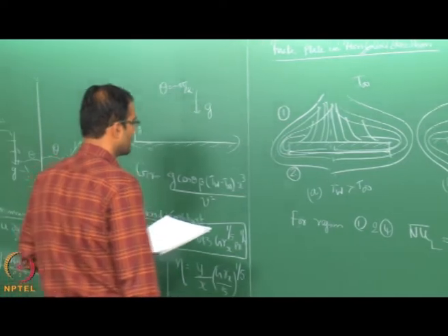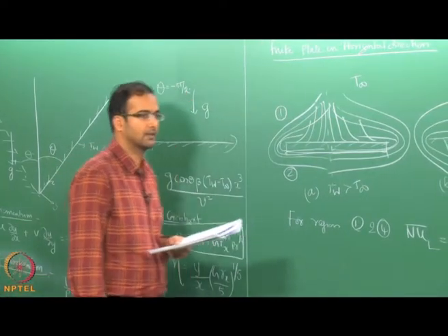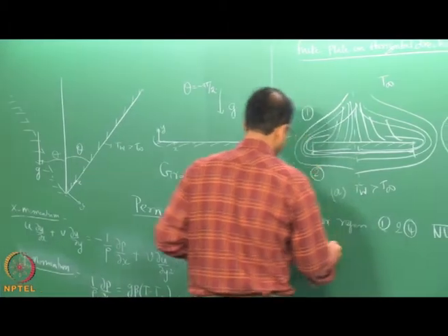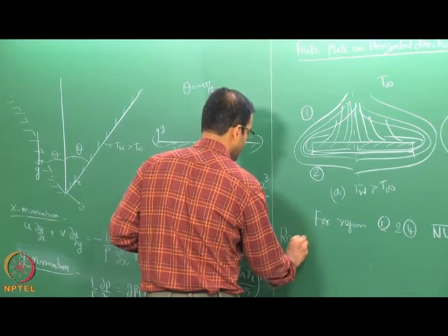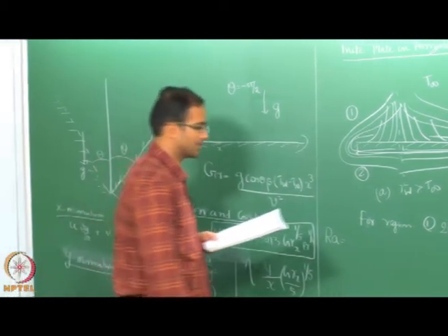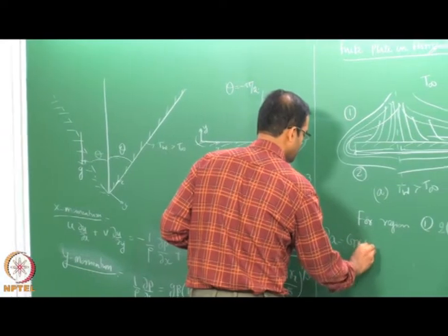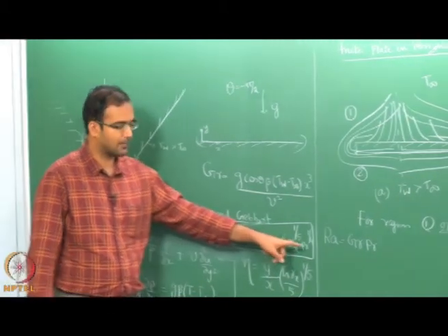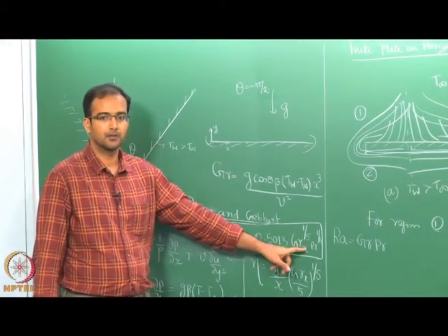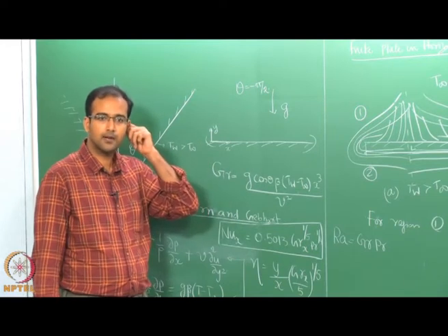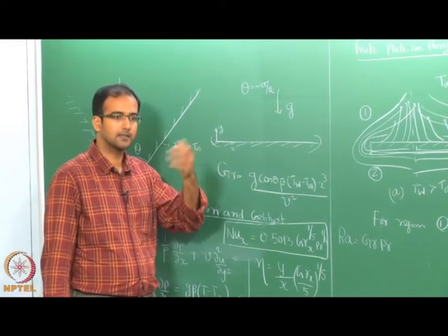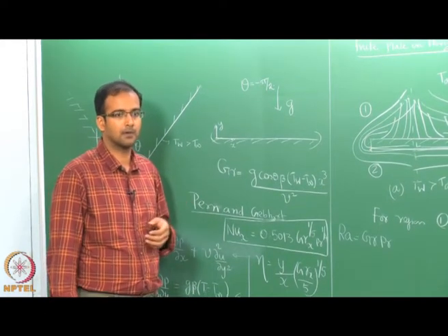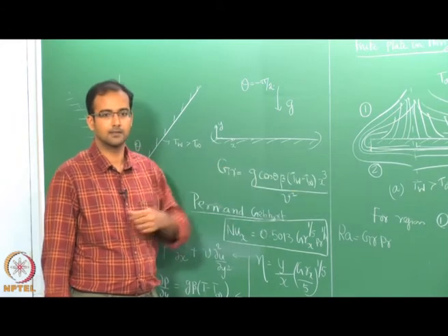Okay. So, so far we have not defined Rayleigh number, right. We have used everything in terms of Grashof number. So, we will define Rayleigh number. Now, Rayleigh number is nothing but another non-dimensional combination of Grashof number into Prandtl number. So, many times you see that Grashof number and Prandtl number come together. In some complex configurations the power of Grashof number and Prandtl number might be identical, such as this case.